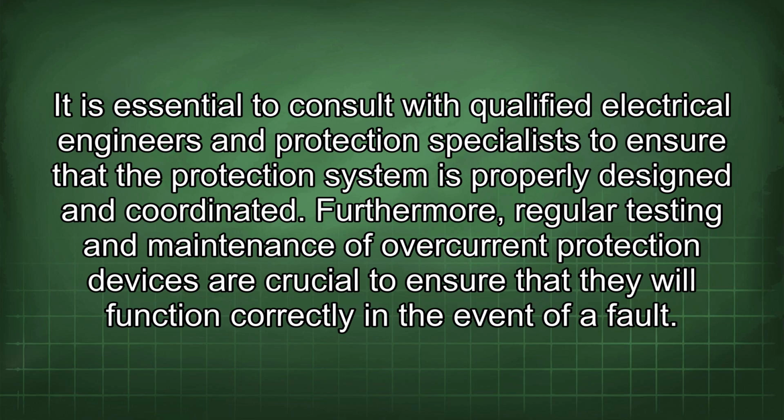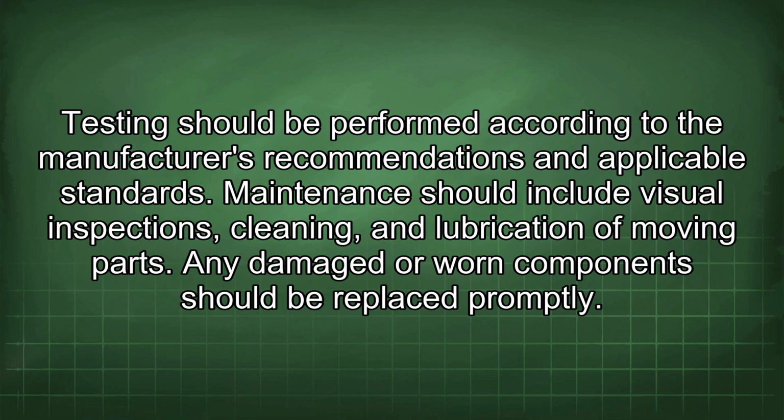Furthermore, regular testing and maintenance of overcurrent protection devices are crucial to ensure that they will function correctly in the event of a fault. Testing should be performed according to the manufacturer's recommendations and applicable standards. Maintenance should include visual inspections, cleaning, and lubrication of moving parts. Any damaged or worn component should be replaced promptly.